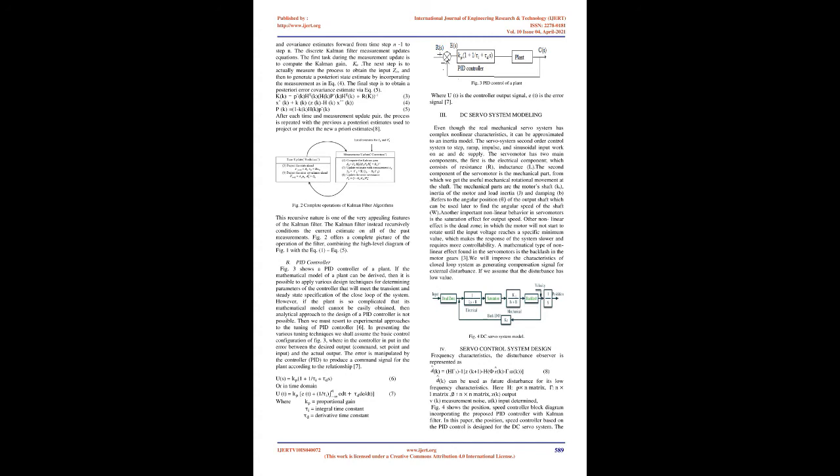The time update equations can also be thought of as predictor equations, while the measurement update equations can be thought of as corrector equations. Indeed, the final estimation algorithm resembles that of a predictor-corrector algorithm for solving numerical problems as shown below in Fig. 1. The specific equations for the time and measurement updates are presented below. The time update equations project the state and covariance estimates forward from time step n-1 to step n. The discrete Kalman filter measurement update equations.